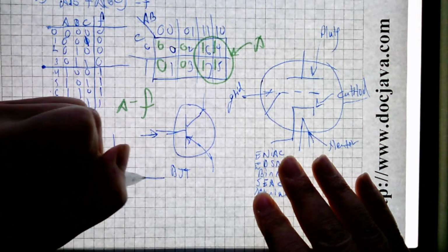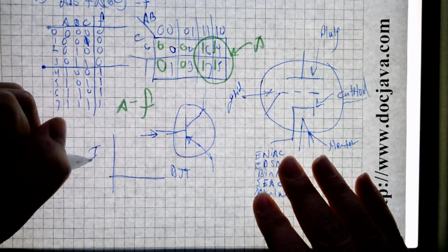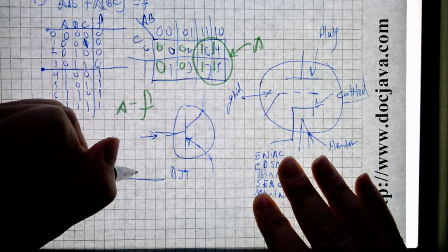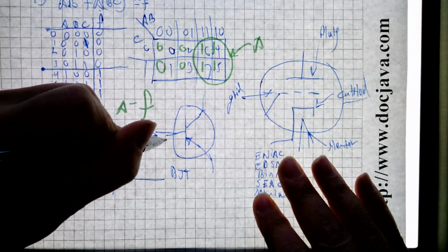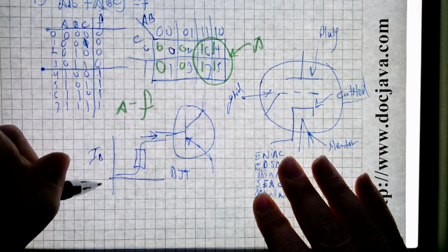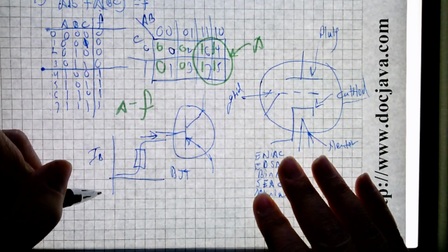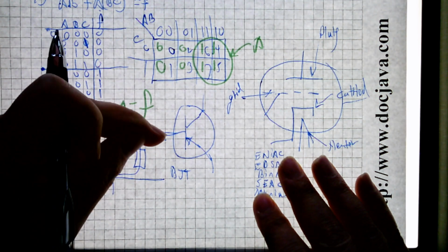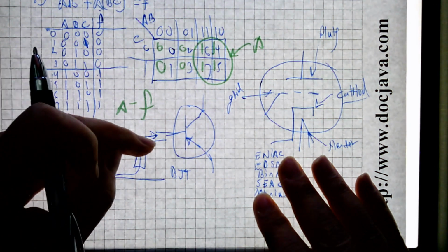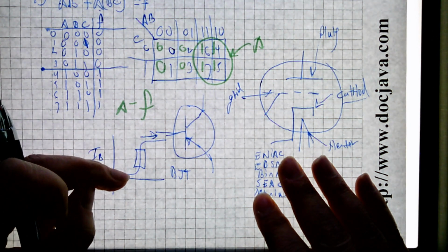So what we do is we look at current into the base, and then we look at the conduction, and there is this linear mode in which we can operate. And if we operate during the linear mode, we can actually make this into a nice linear amplifier. Otherwise, it just slams into one supply rail or then into the other.